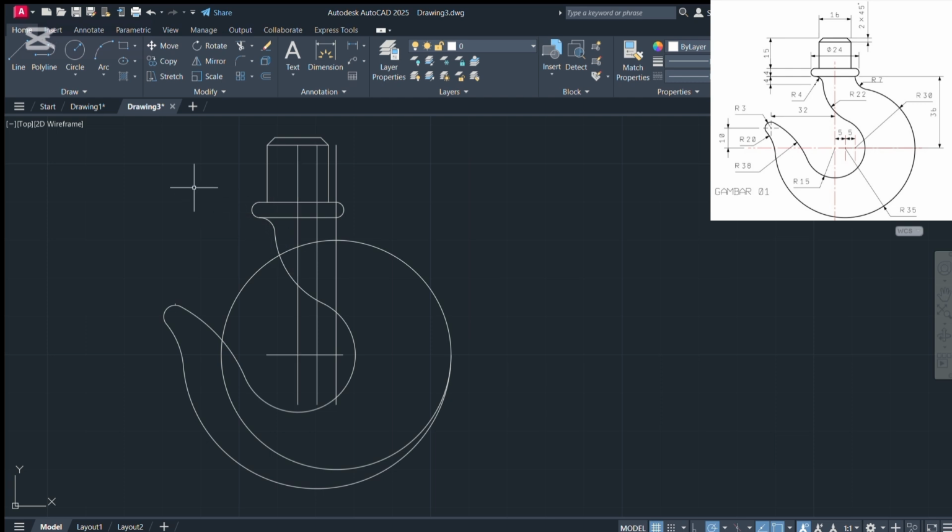Alright, just like that. Then next up, you're going to go to the circle command and choose the tan radius circle command. Then you're going to select the circle and the line that is closest to the outside of the circle, just like you can see in the diagram. I selected the line and the circle, then enter a radius of 7, then a circle like that will appear. Then once that appears, the diagram at this point is particularly, in simplest terms, done.